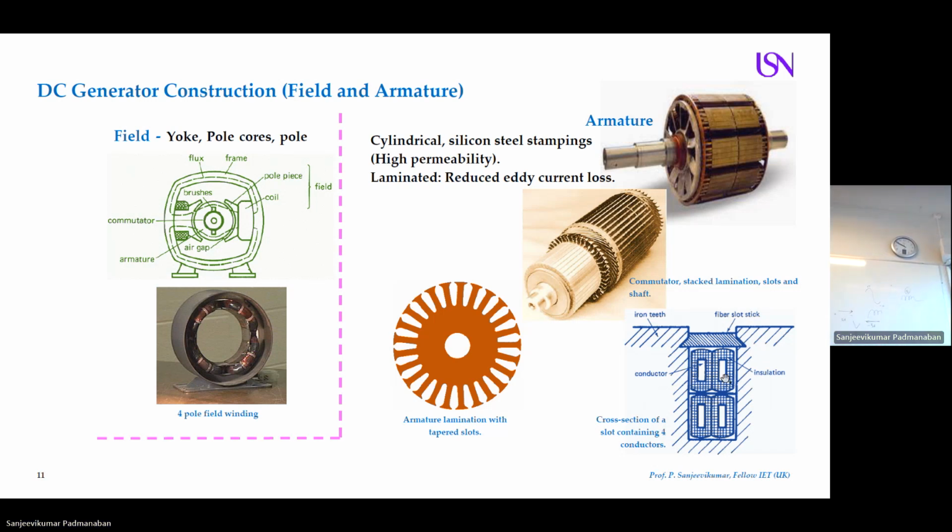Please note, you are looking at a coil here. These individual coils are laminated, insulated. Otherwise, 2 coils can touch and a short circuit can happen. So these coils, either on the field or inside the armature, are completely, fully laminated. It looks like a copper coil, but if you scrape it with a blade, you will get a layer. That's a complete insulation. Two purposes: avoid short circuit between the conductors, and reduce eddy current losses. Clearly?